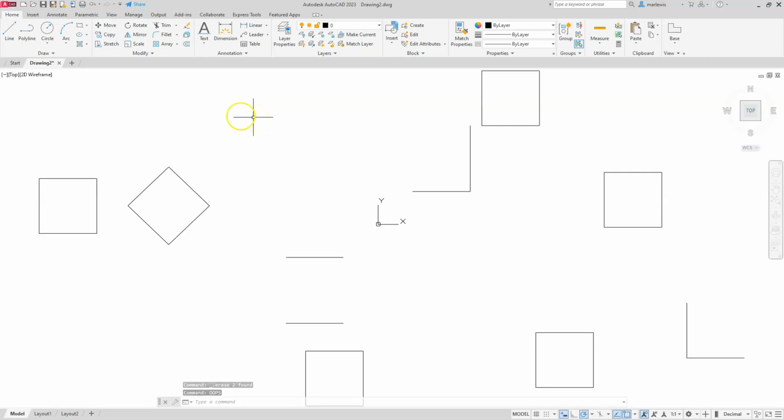All right, so I'm going to draw some more stuff here. I'm going to draw a line going here, and I'm just freehand sketching lines. And remember that I have that rubber banding effect, mainly because ortho is turned off and polar tracking is turned on. And then I can go ahead and erase some more stuff.